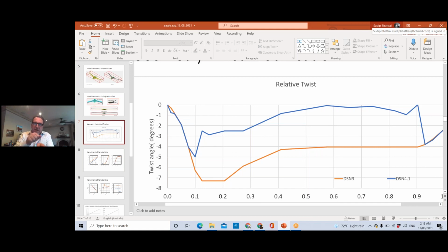But the reason that they do it is not because of the G so much as they do it so that the airplane's in a realistic attitude, getting near stall, and when there's a stall break, when there's a G break, the airplane slides down the hill. It slides down this way, and that induces an immediate side slip.